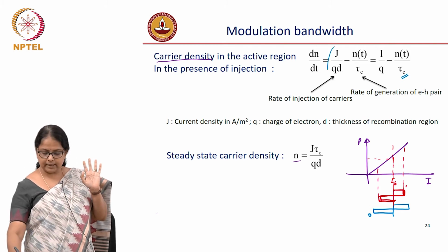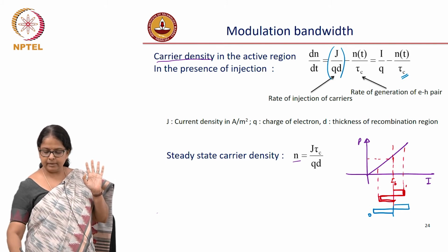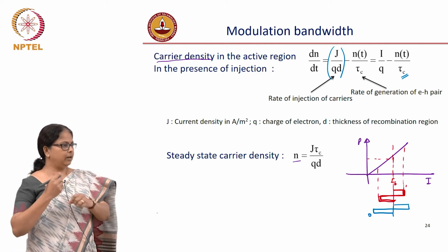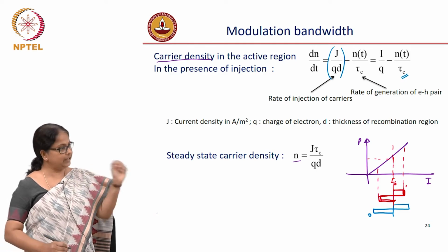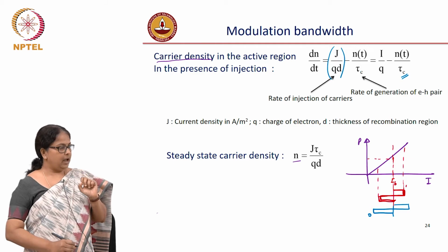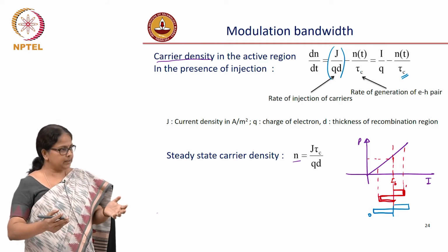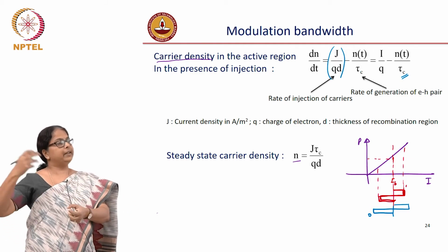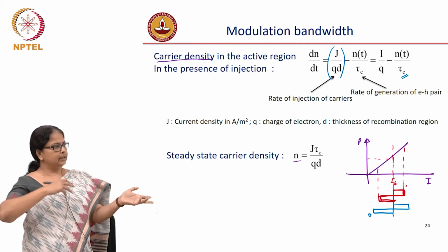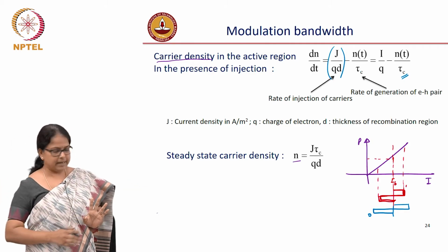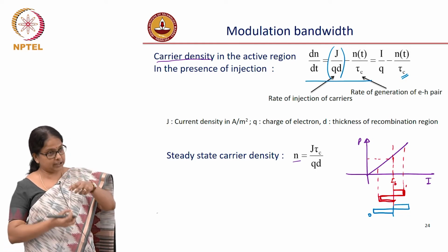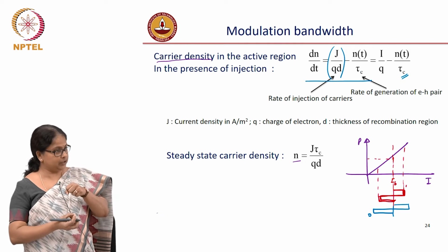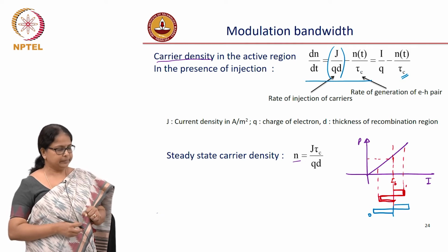So, when you inject a certain number of carriers per time, they are either undergoing radiative or undergoing non-radiative transition. So, this actually includes both, it is not either or, okay. But as a result of the process, the fraction of power that is available at that time, we will consider the radiative part only. But as far as the rate equation is concerned, we have to account for each carrier pair that I have generated, okay.